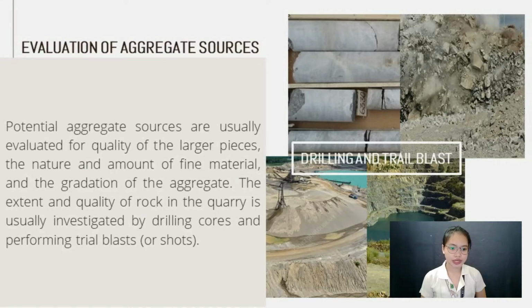Potential aggregate sources are usually evaluated for quality of the larger pieces, the nature and amount of fine material, and the gradation of the aggregate. The extent and quality of rock in the quarry is usually investigated by drilling cores and performing trial blasts or shots.